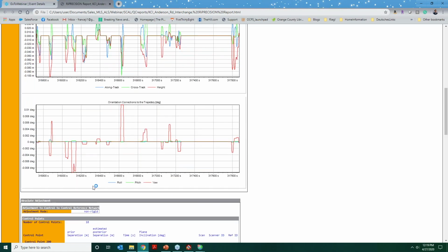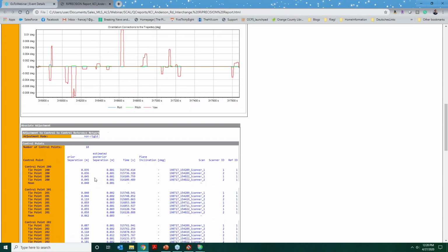So we're able to adjust not just the XYZ positioning, but also the roll, pitch and yaw, which would be known as your heading vector. And you're likely going to see the heading be adjusted more than the roll and pitch because, as you all know from working with GPS, that's the least accurate component of the INS GNSS system overall.